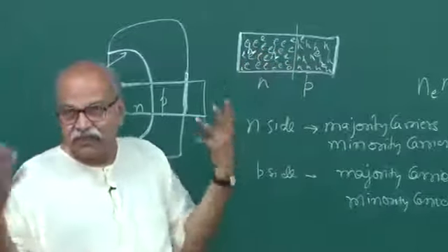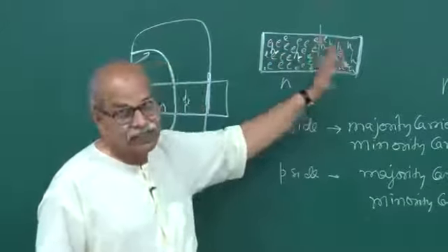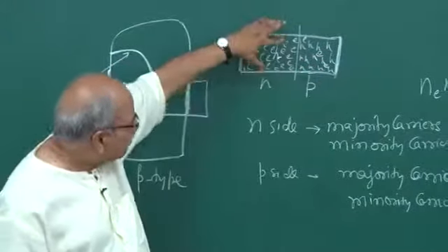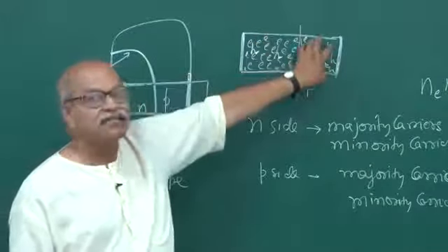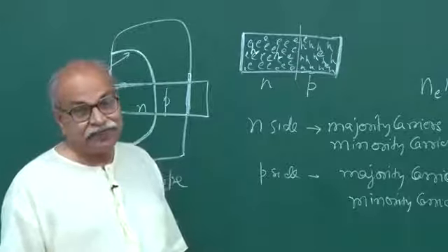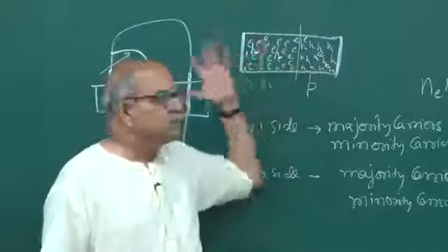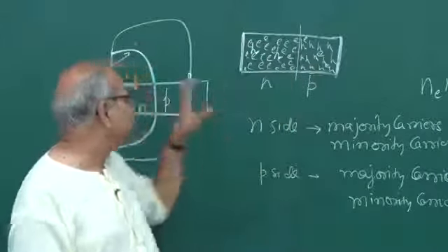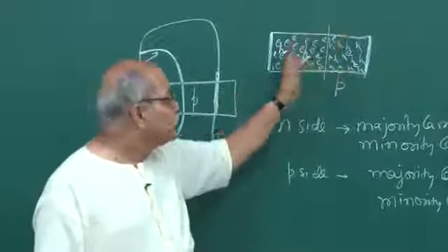So, all that usual electron movement and hole movements is allowed in this entire wafer, in this entire material, and therefore, having large concentration of electrons here and having a very small concentration of electrons here is a very non-equilibrium situation. If you have such a huge concentration gradient, and if the movement is allowed, they are allowed to go from here to here. Remember, the whole thing is one single crystal on which you have done all these diffusions, and therefore, that movement is allowed.